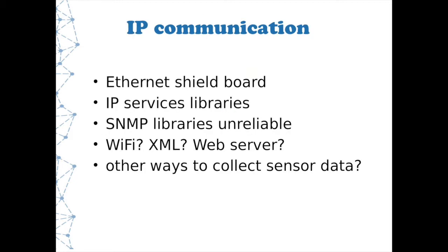Looking at IP communications, I had the option of putting an Ethernet shield on it to speak Ethernet, and adding libraries to work with. What ways could I get data out of it? For example, does it have an SNMP library for network management protocol networks? Does it have web server capability? All these other things. How can I work with the equipment I've got to get the data out that I needed?